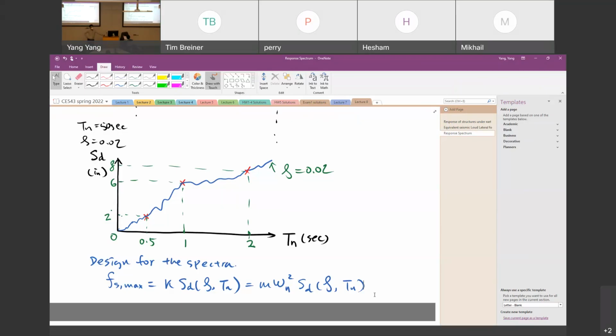If you give me the material properties and the geometry of the structure and ask me to calculate the damping ratio, no, I cannot do that. The only way is to do a dynamic test, either to have the structure do free vibration or to apply an excitation force to have it do forced vibration, so that I can get the information of the damping ratio.